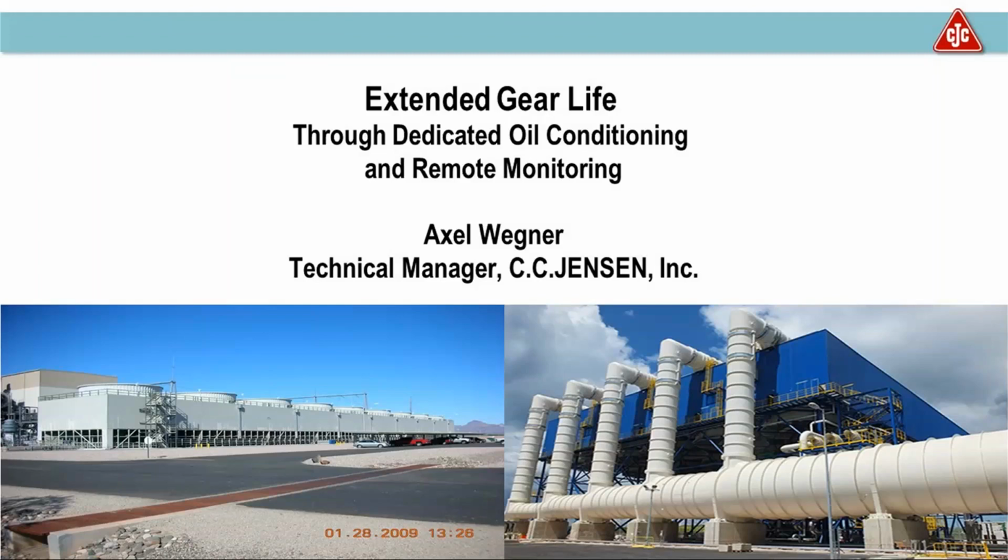I was wondering if, instead of having a mobile unit, you could have one stationary unit, and then have sequencing valves that connect to each of the ACC fan gearboxes, and then every so often actuate those sequencing valves to pull a sample, or maybe even send it to the filter, so that way you don't have a mobile cart, which is kind of labor intensive. Do you have any customers with something like that?